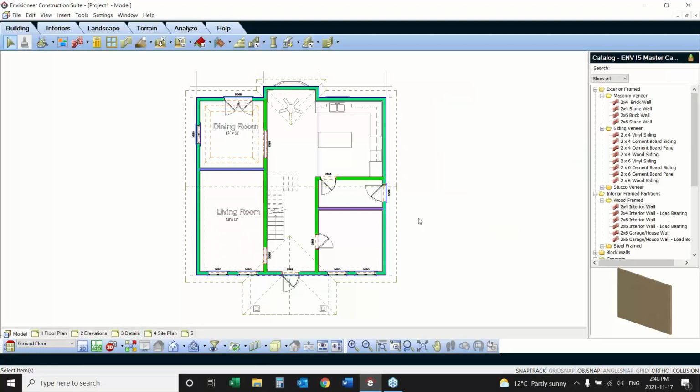But remember, garbage in, garbage out. We give you a lot of different tools to make sure that that PDF is accurate. Make sure you have the right scale. If it can be a scanned PDF, you're going to have to zoom in. If it's a CAD-based PDF from the beginning, then it's more accurate and you can pick more accurate corners. Use the tools at the top of the screen.